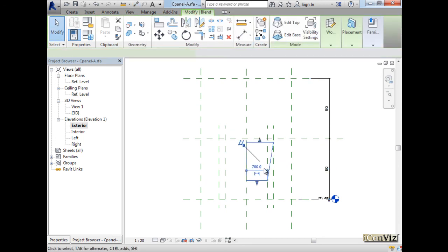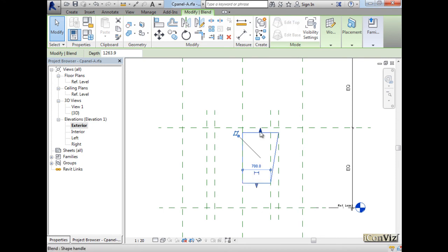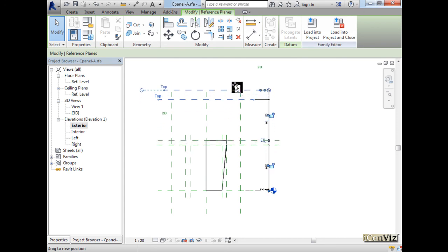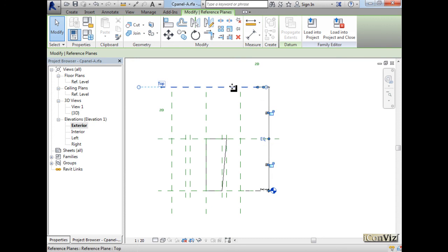Then I will stretch the geometry. Watch me here please. Once you stretch this here, lock it and lock it here. So whatever the height of the panel in your project environment, if it's a small curtain panel, the curtain system grid, if it's 2 meters by 3 meters or 5 by 3, this quarter of the hexagon will remain where it should be.